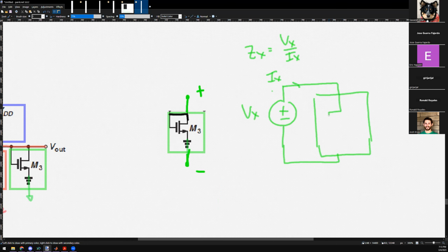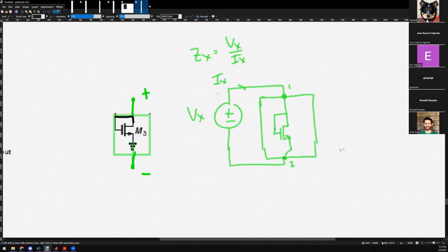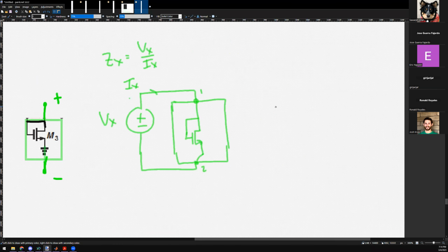So in here, I basically have this NMOS device. And because I drew a box, any box that is only pierced twice has an equivalent impedance. You got it? All right, let's figure out what the impedance is. What's the small signal model of any MOSFET? Gate, source, drain. I have a resistor R naught, and I have a current source, GM VGS.